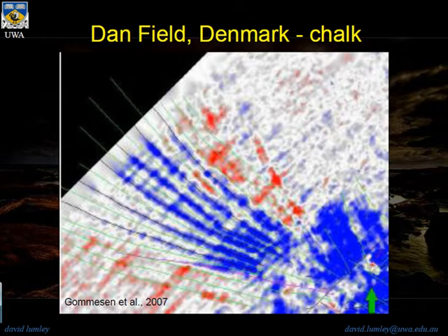But you can see the 4D is showing that's not happening. The water is staying very close to the injectors, and in fact on the periphery we're getting red popping out because the producers are depleting the pressure, they're not getting water support, and gas is popping out of solution. This image shows very nicely how well or not how well your reservoir model and assumptions are working there, in terms of the water staying pretty close to the injectors and not doing a great job supporting the producers.